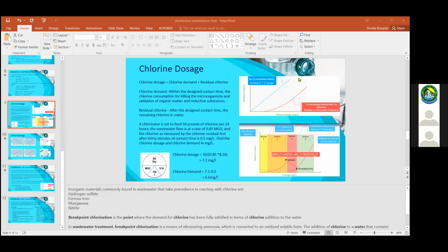You'll have very little TSS, no ammonia, no phosphorus. You can do your heavy metals check, you will not see anything, and then you will do a fecal coliform test, and you will get a fecal coliform value that is above your limit. Sometimes, if they do this tube test, they may get greater than 1600, and you'll be like, so how do I get this very high fecal coliforms? And this is what happens.